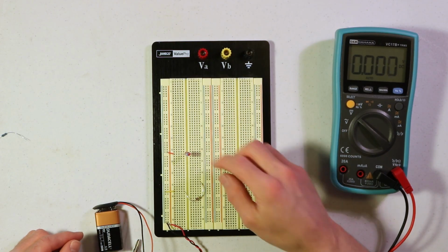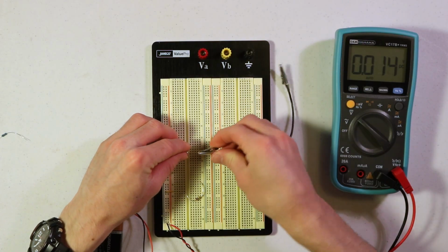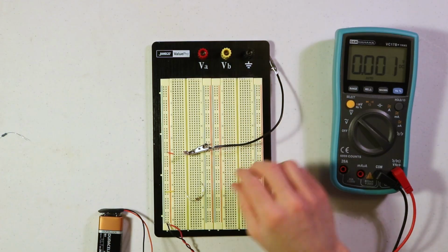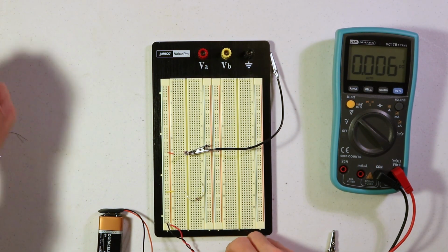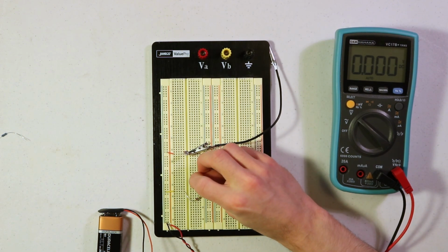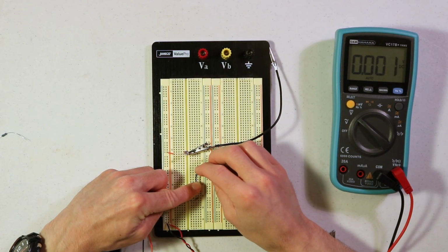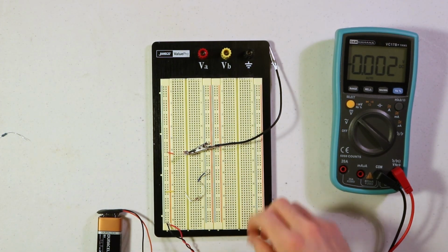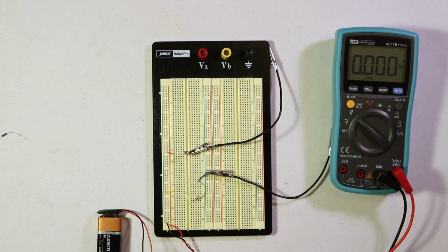So now we've got a break in our circuit, and this is where we can attach our multimeter to measure the current. So just take one of your cables and clip that on the side of your LED, so that's on the negative side of the LED. And I'm just going to grab another wire here. I could just clip it to the resistor, but I want to be able to swap out the resistors and see how the current changes. So I'm just going to plug that in there and leave it sticking up. So now I can clip the other alligator wire to that.